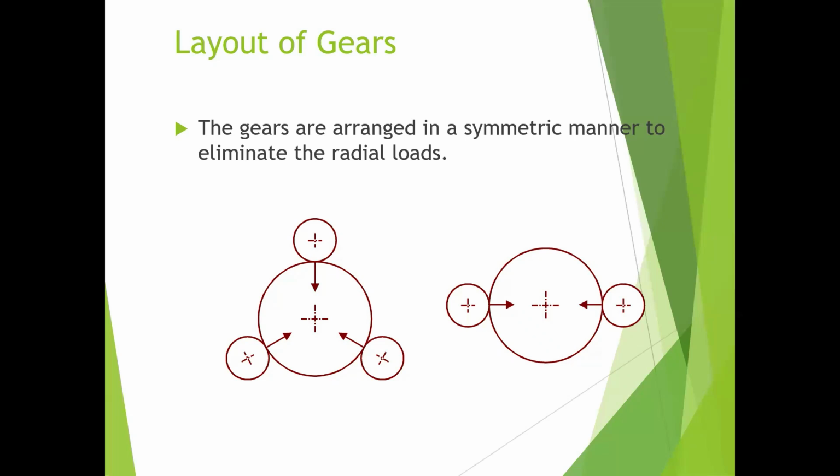So then the system will be statically balanced. If you have 2 gears, I'll also make sure of it. So with these 2 small gears, the radial force from here and the radial force from here compensate each other also.